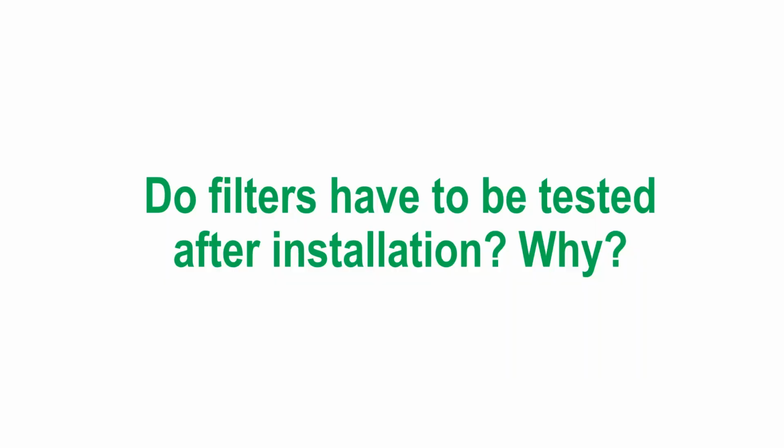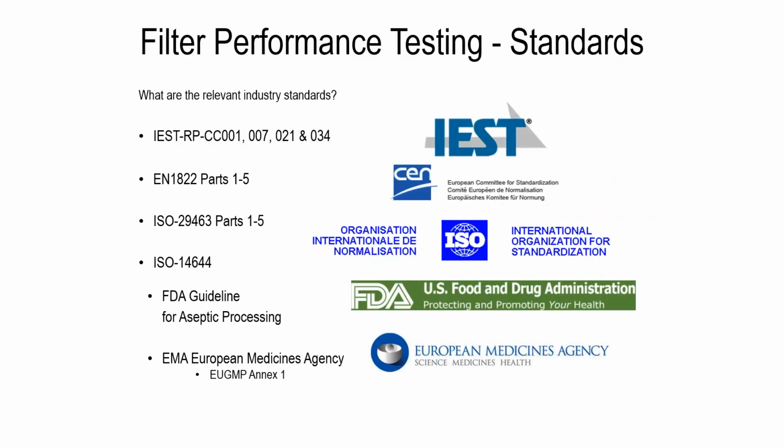So do filters have to be tested after installation? Yes, they do. And why is that? Because obviously during installation, you have very fragile material such as microglass. You could have damage to the media. The other issue that we run into is the actual frames matching up with the HEPA filters.